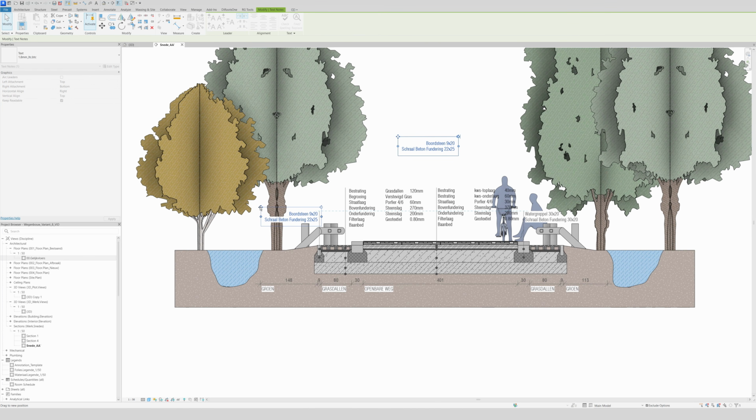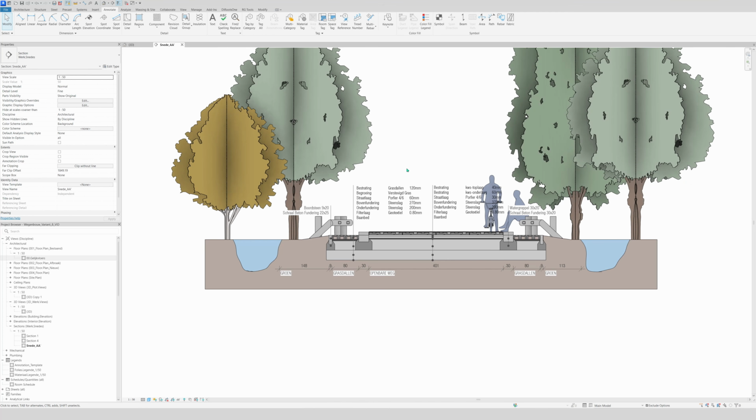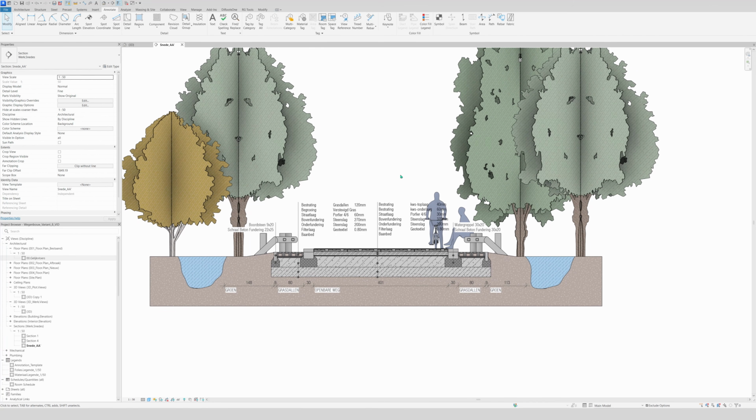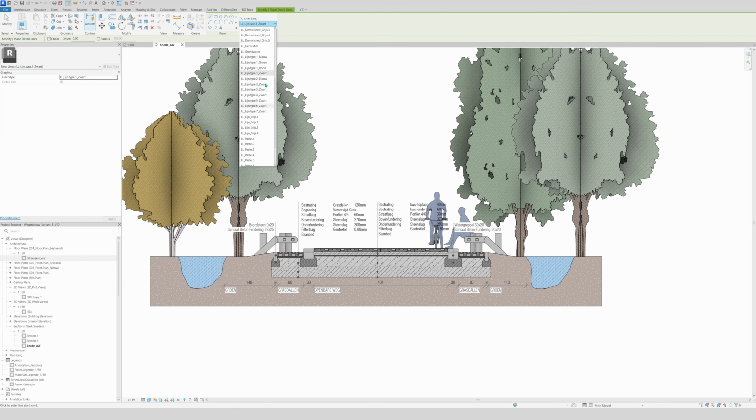You see now the blue line. That means it's the same height as this one. So we want that, of course, and just leave it like this, and voila. Now, there we have it. The other thing that we need to do right here in our country is specify where the middle of the road is, so the center line. We will do that again by going to detail line, shortcut DL, and then I have a line style I made, the center, and then we're gonna look for the center right here, and we're gonna draw it to there.